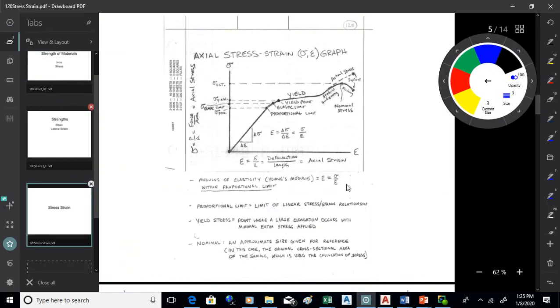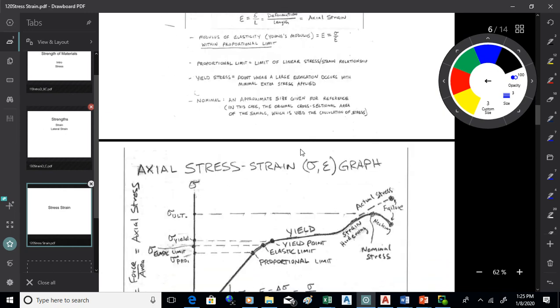All right, so hopefully you've had a look at those three videos. The one thing I'll point out is that in the first one, the graph was load versus elongation. The actual graph that's used, at least in this country, is stress and strain. So you do have to remember to convert load into stress and elongation into strain. Okay. So let's have a look here on page 126, I think it is, at this graph.